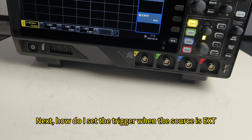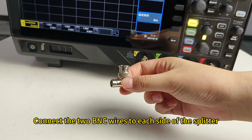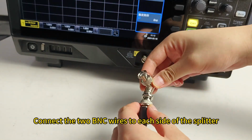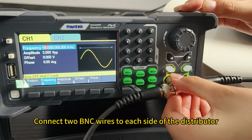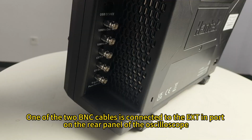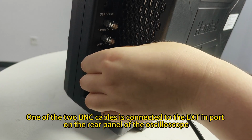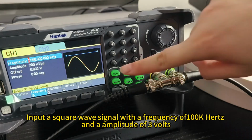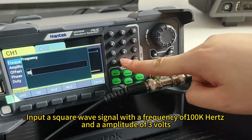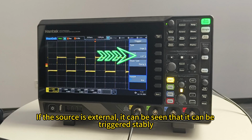Next, how do I set the trigger when the source is external? We need a splitter and 2 BNC wires. Connect the 2 BNC wires to each side of the splitter. One of the 2 BNC cables is connected to the EXT port on the rear panel of the oscilloscope, and the other to channel 1. Input a square wave signal with a frequency of 100,000 Hz and an amplitude of 3 volts. If the source is external, it can be seen that it can be triggered stably.